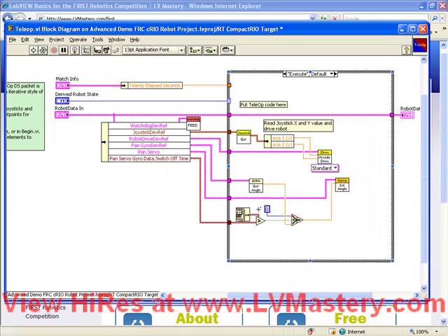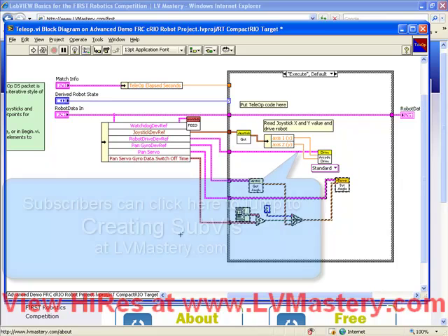And now what we wanted to do was modularize this code. So we already have pretty much all the functionality we want, except that we only have it working on the pan gyro, the pan servo, and the pan servo gyro data. So what we want to do is actually select all of this functionality and make a SubVI from it. We've talked before about how it's possible to create your own SubVIs. Now I'm going to demonstrate to you two different ways to do it.